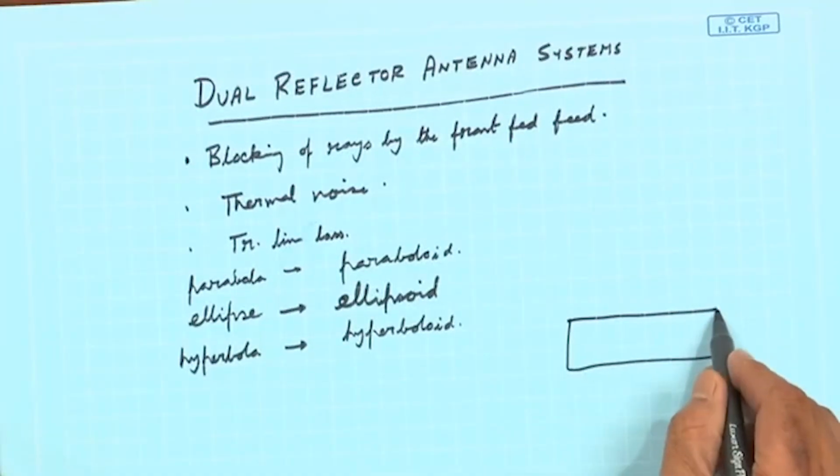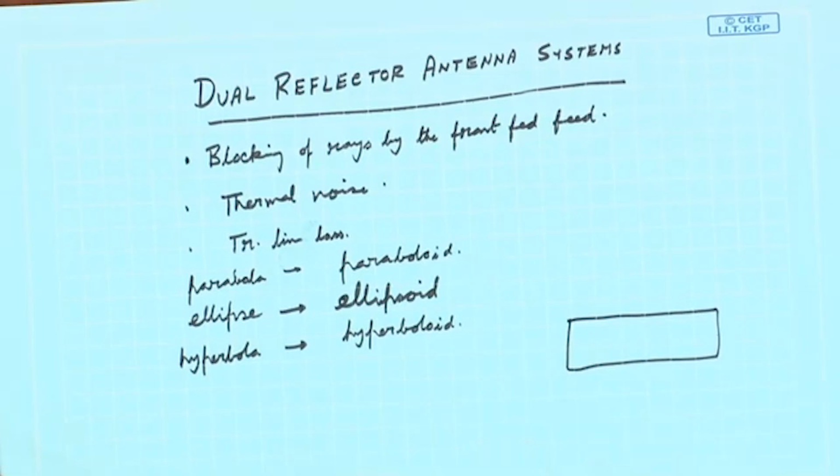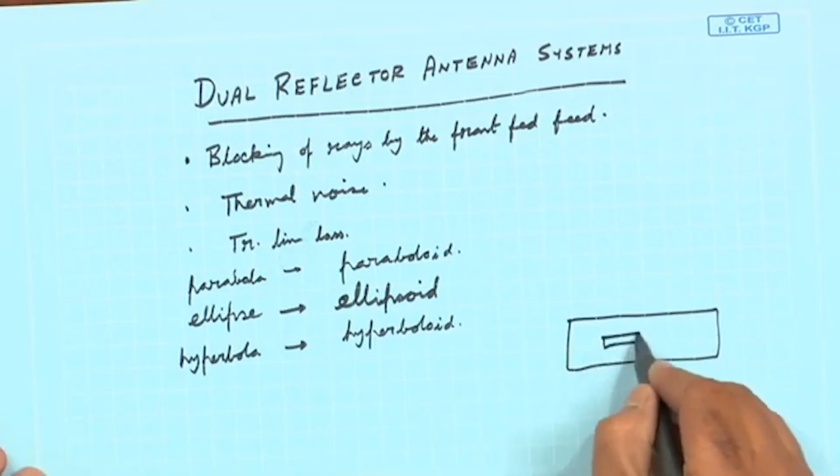But if you have a curved surface, suppose a cylinder or a sphere on which an aperture is cut, you cannot use this technique, because you cannot find the field. Similarly, suppose I have an open end waveguide and on its top wall I cut a slot. Now, what is the field distribution there?